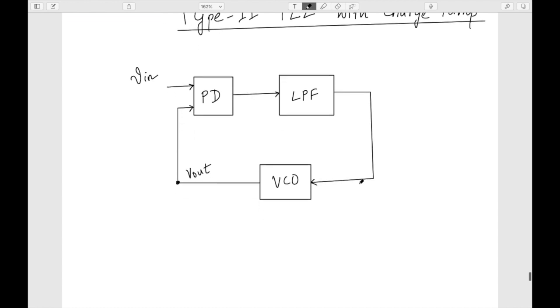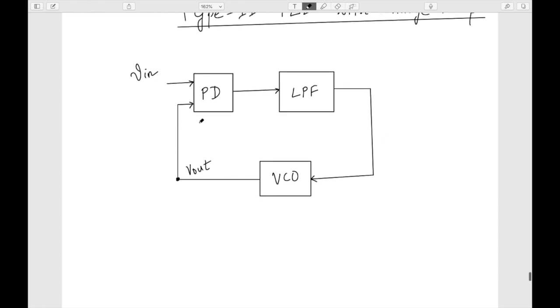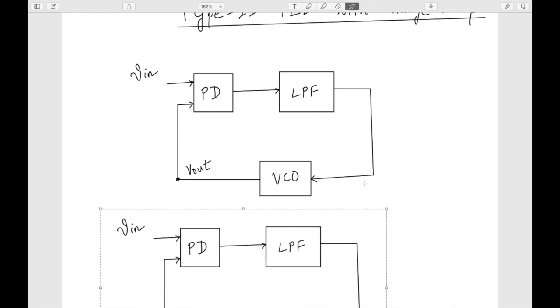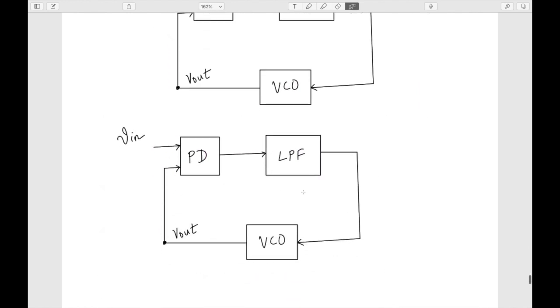So what we want is, if there is a large difference in the frequency between V in and V out, we want it to detect the difference in the frequency and lock it first. So what I basically want is a frequency detector which can find out the difference between this frequency and quickly tell the VCO that look, there's a lot of difference in the frequency, so bring omega in and omega out, the difference between them, very small. But of course, as we have mentioned, an FLL alone doesn't work, because we cannot make it perfectly the same; there can be an offset.